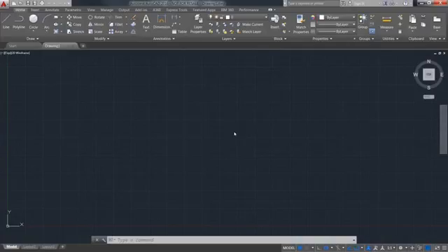For today's demonstration, I'll be using AutoCAD 2016. And let's start up a brand new drawing. As you can see, there's a blank one. As Scott covered last time, even just the act of starting a new drawing has several options. We can start with a blank new drawing or with a predefined template file, or there's even an older wizard you can access to get in, and it'll ask you questions like, what do you want your units to be? What do you want your angles to be shown in?